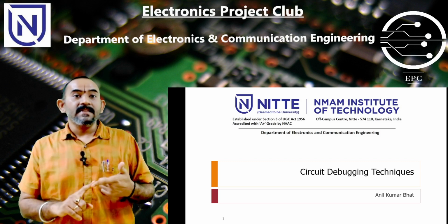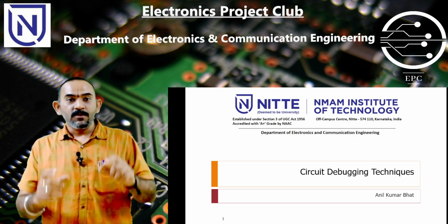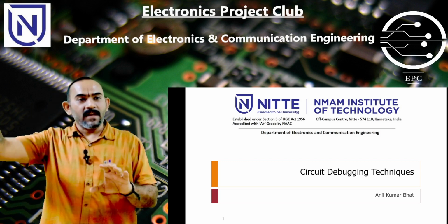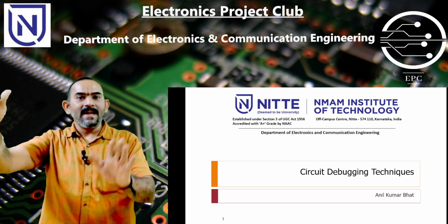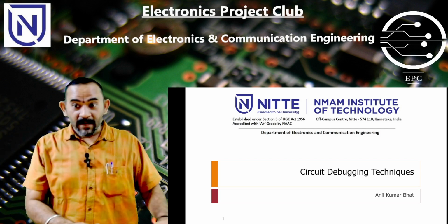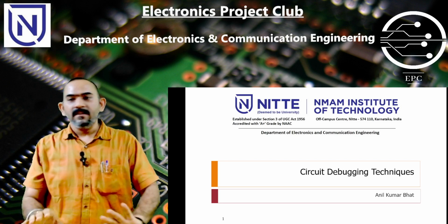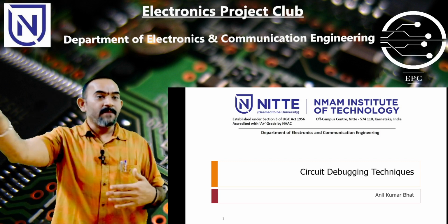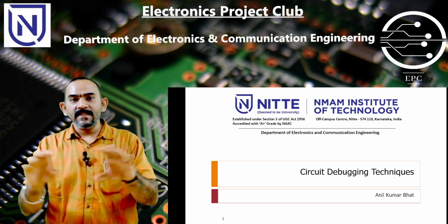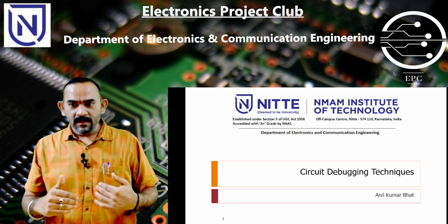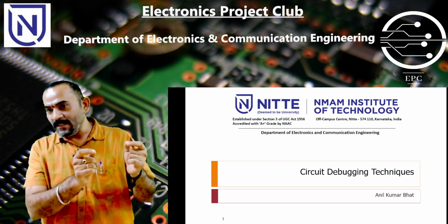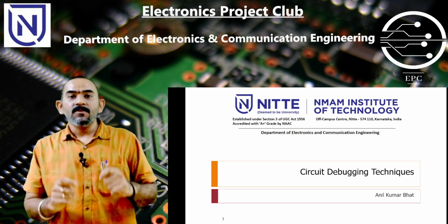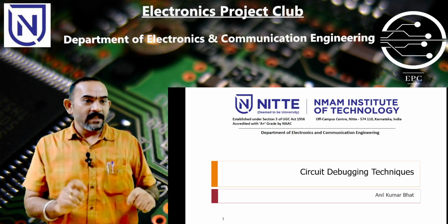Then there is something known as a prototype test. The functionality test can be done via simulation. So I come up with a simulation, and I know that this works in this fashion. Then I build that circuit on a breadboard and see whether it works. It works fine. Then I do a PCB routing layout and send my product for fabrication. Once it gets fabricated, the board comes to me. What I have now is a prototype of the board, basically a similar version of how the final product is going to be. So I have to test that. That is known as prototype testing.